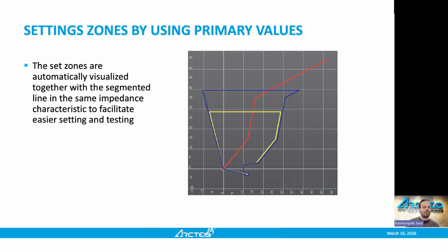So now we are following the resistive reach of all 3 protected lines. And if we would put only that we follow the resistive reach of line 1, this angle here would not change, but it would proceed like this. So this is where we actually need to put the setting value 3, like we are also doing with the line protection.